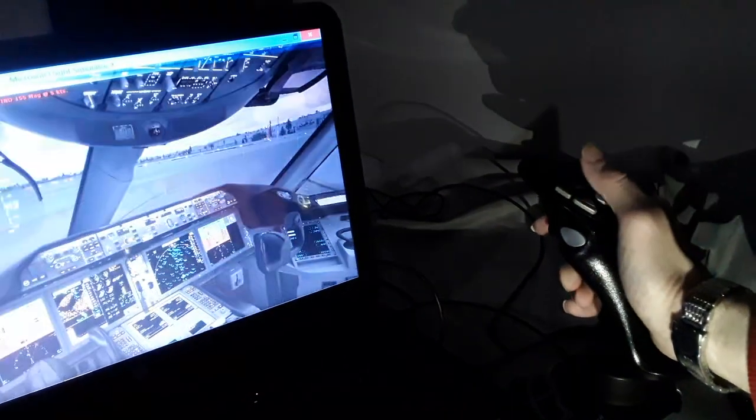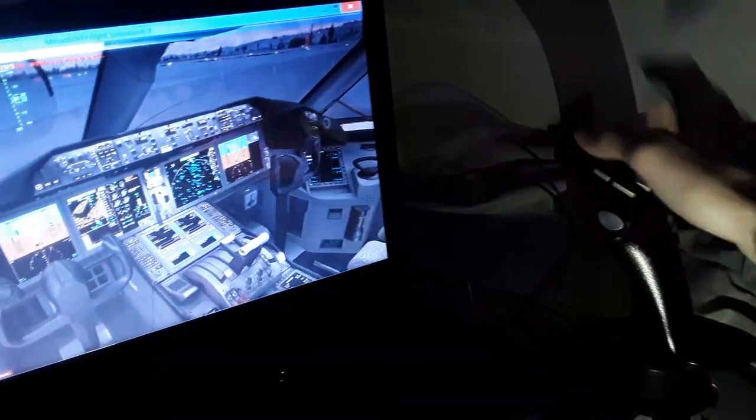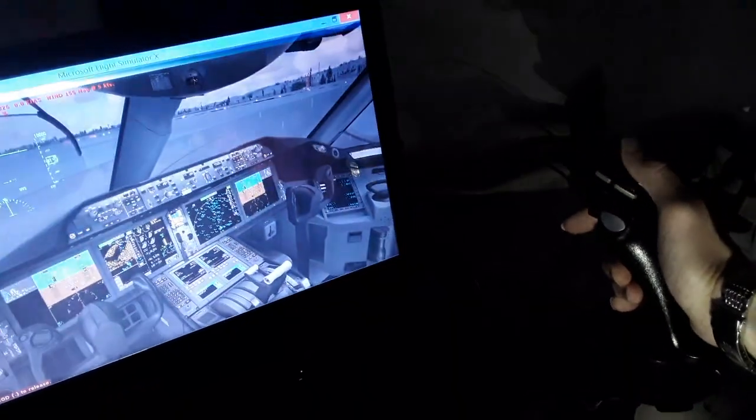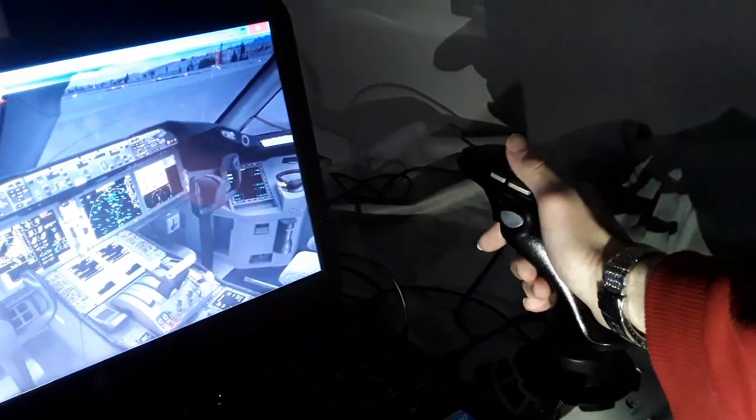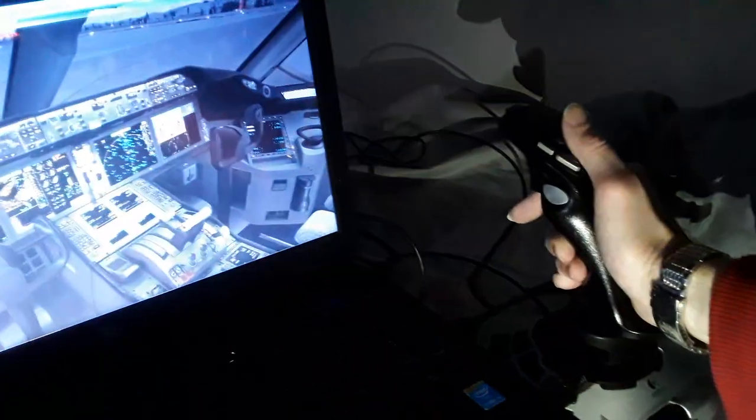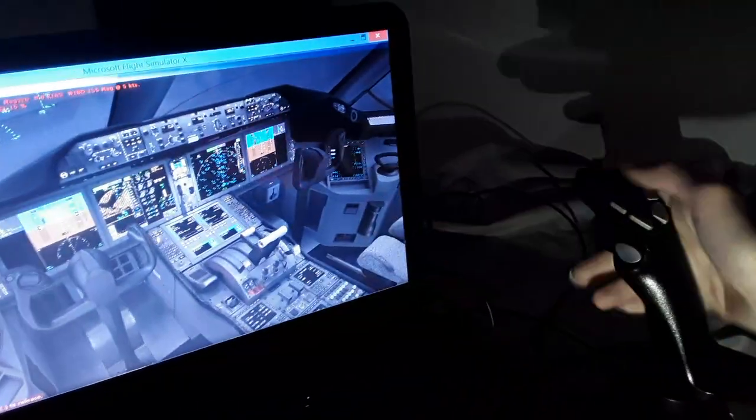Velocity lowest selectable and maximum velocity. So we have speed limits and speed protections, and the G limit. Also when we fly level in the Airbus aircraft, we have 1G acceleration vertically through the axis of the aircraft to maintain using the auto trim, the horizontal stabilizer, and the other flight controls. Also the Boeing has similar features.